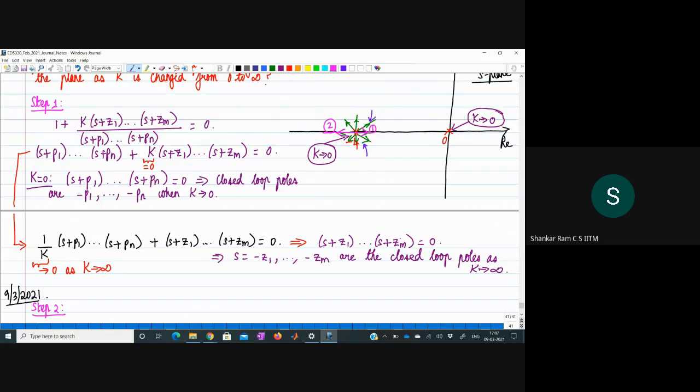But then we eliminated all directions other than those along the real axis by arguing that if the branch which starts from the pole at -4 goes into the complex plane, its mirror image should also be a branch. Because we are considering polynomials with real coefficients, if we have a complex root, its conjugate also must be a root. That eliminates the possibility of a branch from a non-repeating open loop pole, such as that at -4, going into the complex plane directly.